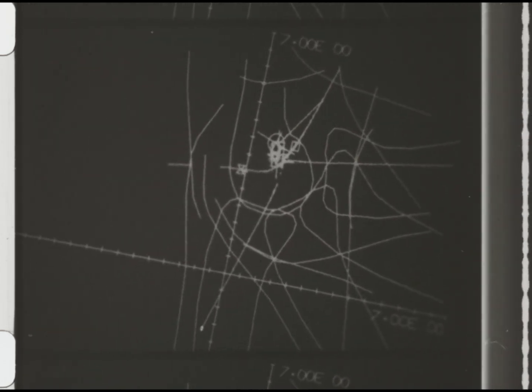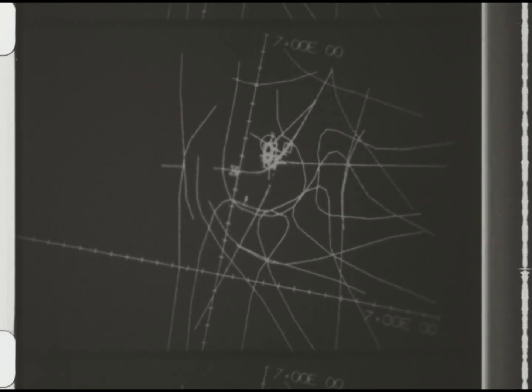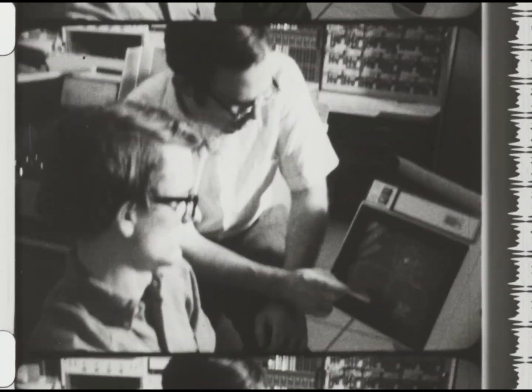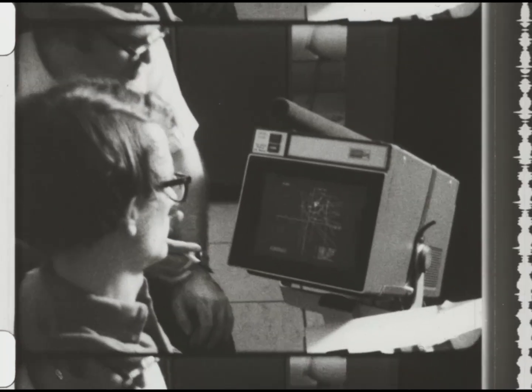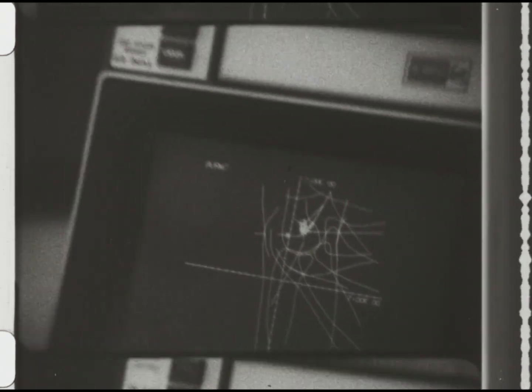In addition, whenever he stops the spot to study a particular choice or a particular potential choice of a linkage, the computer gives him some additional design information by flashing whether or not the linkage is acceptable, meaning that the linkage would be capable of moving the body through the specified design positions, whether the linkage would be capable of moving the body through the design positions, but would require guidance through certain collinearity positions when two links lined up with one another, for example, or whether the linkage would be unacceptable in the sense of being unable to be assembled in each of the design positions and move continuously between these positions.